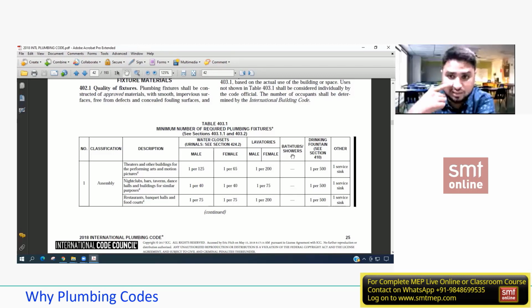4. Exactly. I can say 3, but not exactly 3, because it's more than 3, so I'll be going on the higher side. If you do the calculation, you'll get 3.5. I can't say 3.5 showers or 3.25 showers. I'll directly say 4 showers to be on the safer side, because one shower is required for 15 prisoners and we have a capacity of 50. If I divide that by 15, I'll get 3 point something, so I'll go with 4. Hope you guys are following.